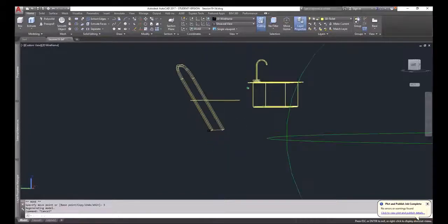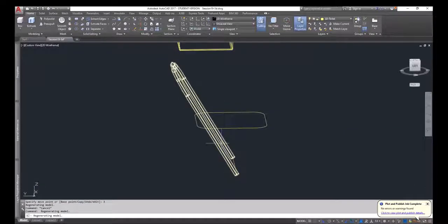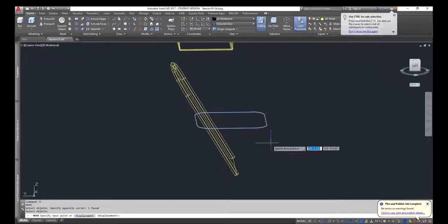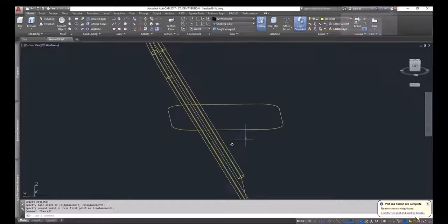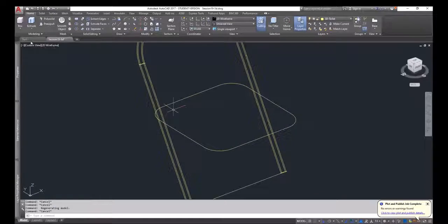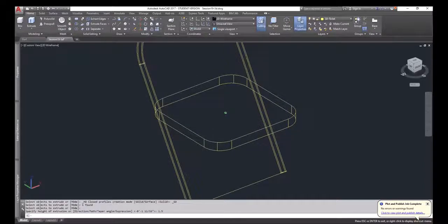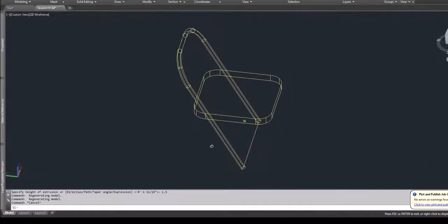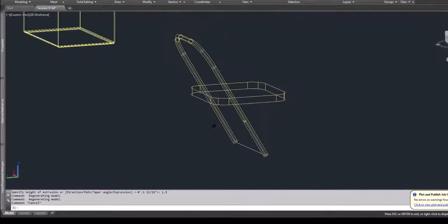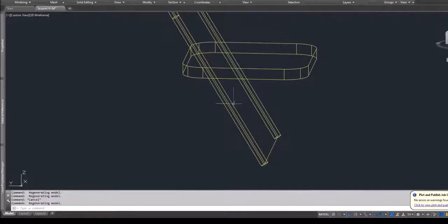Right, that looks a little bit better. Maybe it needs to move back a hair. Then I could extrude this like 1.5 inches because that's the seat. It's starting to come together. So one piece at a time. All right, once I have that there, now I can draw the pieces that go along here.